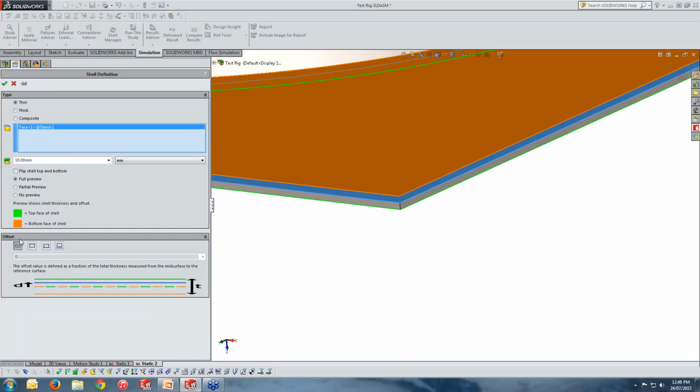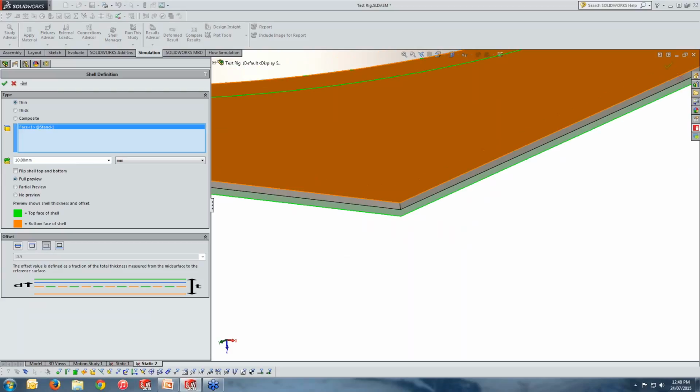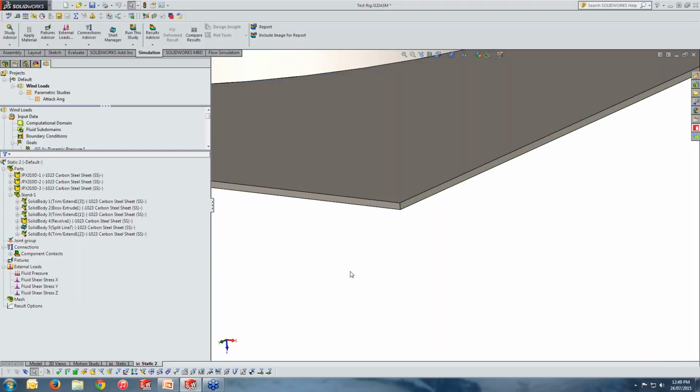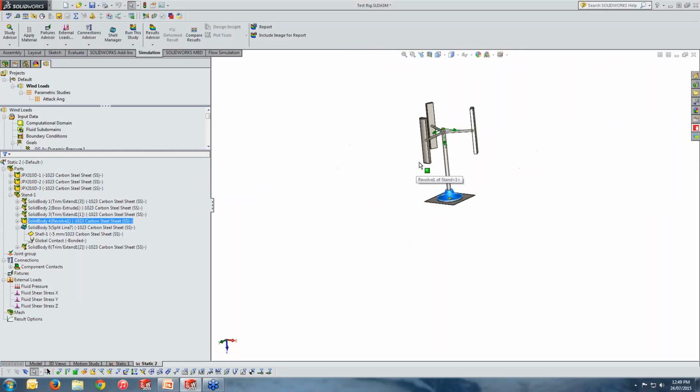Now I can go to the offset scheme, make sure it is located in the correct direction. So the thickness should be 5, and right now the orange and the green planes are simply showing us the thickness of this shell. So clicking OK, and I've converted my model to a shell here, solid here, and beams on here, again solids on the other components. Alrighty guys, now material setup and beam joints are set up.